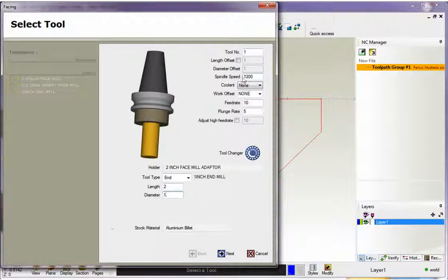Okay, so here's your spindle speed, and here's your 2 different feed rates. You can have OneCNC calculate the spindle speed and feed rates automatically, but in this example I'm just going to type things in manually here. So I'm going to type in, how about 2400 RPM for the spindle speed.